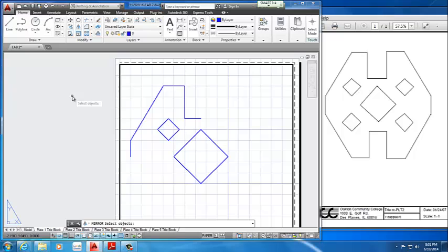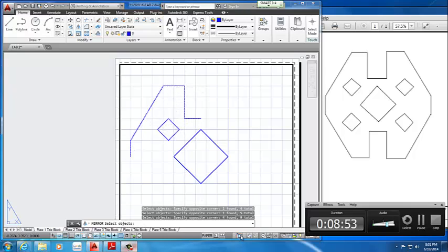If you can't find it and you're wasting time looking for it, you might as well just type it in. You'll maybe remind yourself where it was later on. So we select the mirror command. We select the objects we want to mirror, which is going to be all these lines. So we have about 1, 2, 3, 4, 5, 6, 7, 8, 9 lines. Select the object first and then.